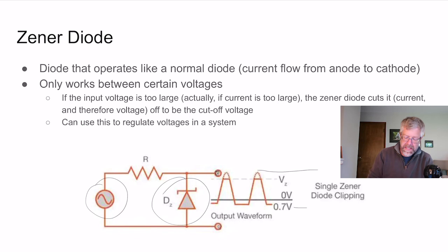And what you see is that the voltage is going up for a little bit. Instead of going all the way up to the high voltage, it actually is cutting off at this certain voltage. And the Zener diode here is basically limiting that voltage to stop at that certain voltage. And then this oscillating voltage is coming back down, and it comes back up, it stops there, and then it comes back down. And so a Zener diode is limiting the voltage so it won't go above a certain level.